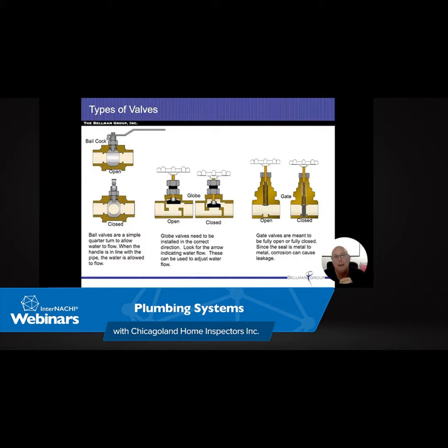And then we also have air flowing through those pipes as well. Now, if it's only air, so these are the pipes that go up and out through the roof, those are going to be vents. All right. So typically it's going to be a vent stack. There is some configurations, and I'll show you some pictures in a little bit, where we can have a vent pipe coming in there, so it'll be horizontal run.